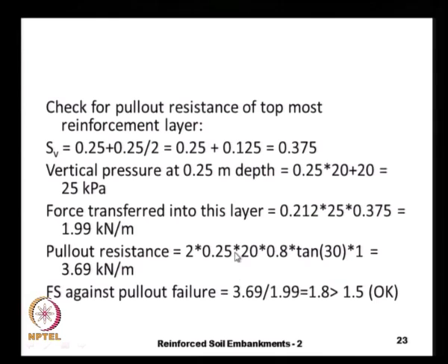is 2 times 0.25 times 20, where 0.25 is the height of the soil, because here I am ignoring the effect of surcharge. As per the codal requirements we should ignore the effect of live load surcharge on the pull out resistance, because that is the worst case scenario. Actually that is also as per case B of BS 8006. The pull out interaction parameter is 0.8, and this 2 is because we have the shear force developed on both the surfaces, times tan 30 times 1, which is the embedment length, that is 3.69 kilonewtons per meter.